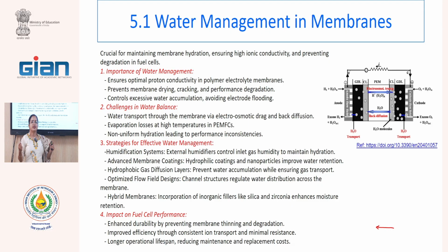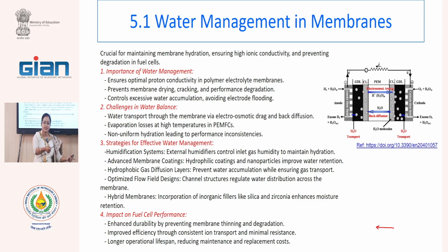Mass transport, right? If we all recall our Fick's law, J equals minus D dc/dz. All of us know that. Whenever we have a negative concentration gradient, our mass flux comes into picture. So when I have a negative concentration gradient in this direction, my water will try to go from cathode to anode side. And what direction do I prefer? Because water is carrying the H plus, what direction should I prefer? I want H plus to go in the opposite direction, from anode to cathode, right.